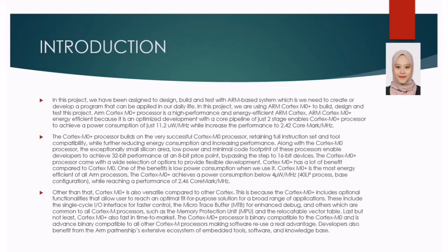The benefit is low power consumption when used. Cortex-M0+ is the most energy efficient of all ARM processors. The Cortex-M0+ achieves a power consumption below 4 microwatt per megahertz, which is a 40 LP process based configuration, while reaching a performance of 2.46 CoreMark per megahertz.